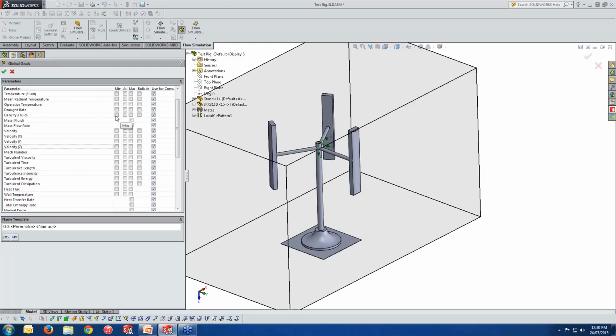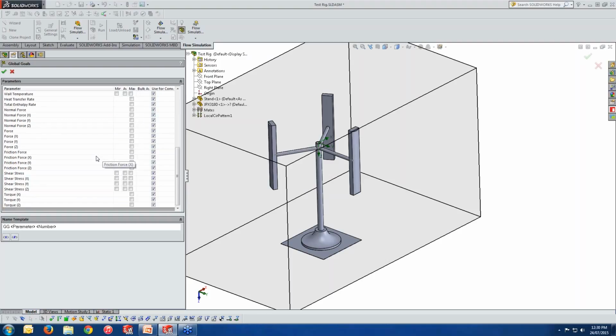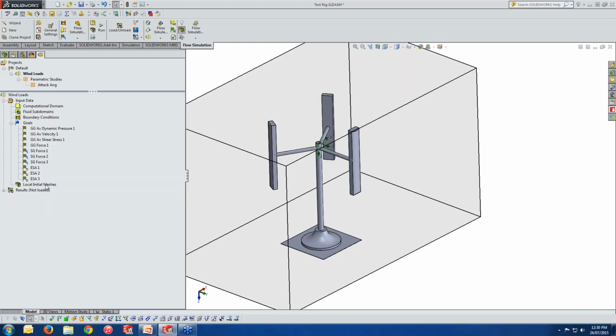Since you're creating that density, then again you can recall it in your equation goal. So what we understood, there is a big list of parameters. Well, they can separately be traced. If you have a specific formula to trace the result on, then you have to use any of these, combine them using the mathematical operation to create an equation goal.